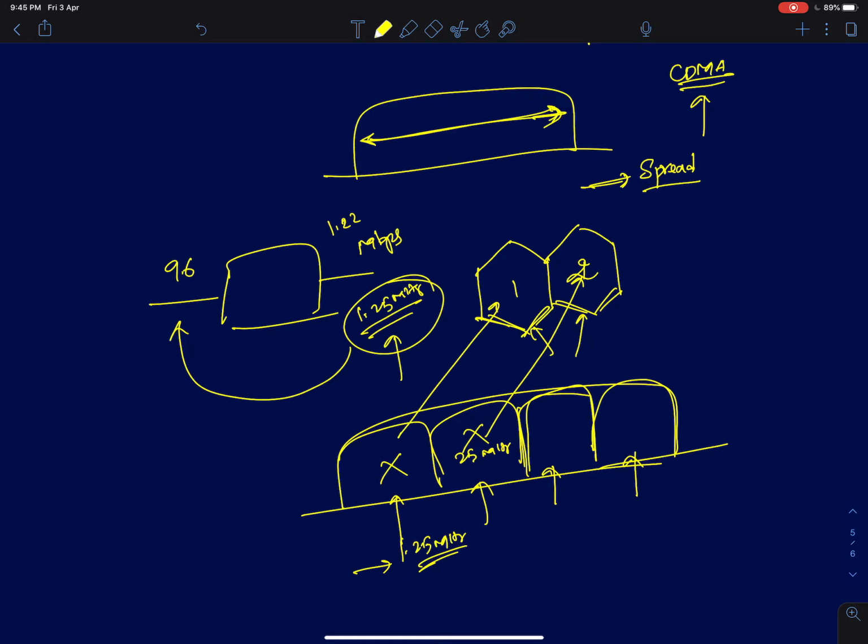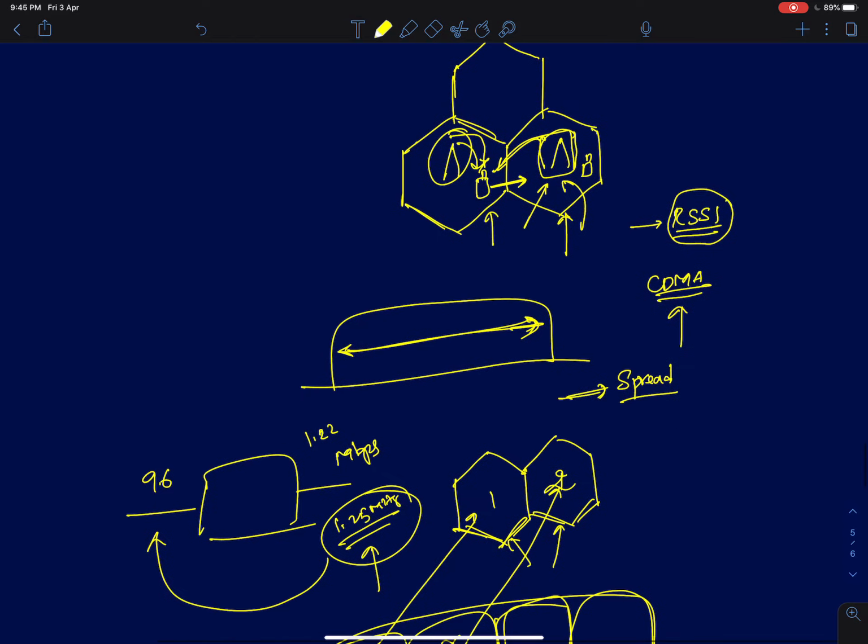Okay, so that's the only point which I wanted to talk about CDMA, that the handoff can be made really much more, it can happen in a way, the handoff can happen very subtly here in a CDMA system. Okay, both the transmit towers will transmit using the same code, and that's like a huge benefit for the cell phone, because it can now exploit extra signal power in the same bandwidth.